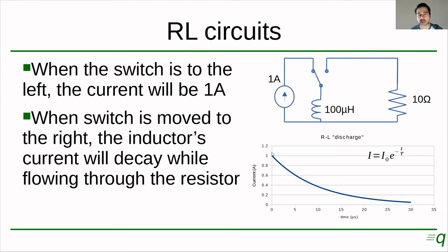And the current is going to decay to 0 amps after a time constant that is defined by the inductance and the resistance here. So the current through the inductor is going to decrease slowly. And by slowly, I mean just not instantaneously, because the decay is going to be pretty fast, right? This scale, as you can see, is measured in microseconds.